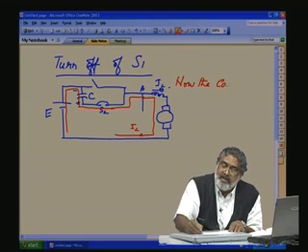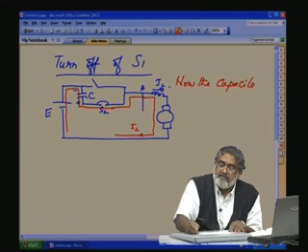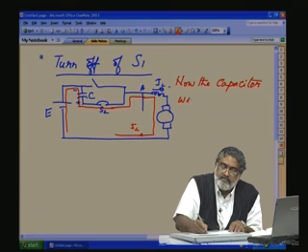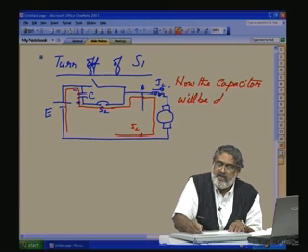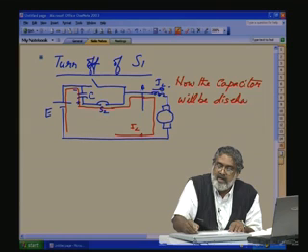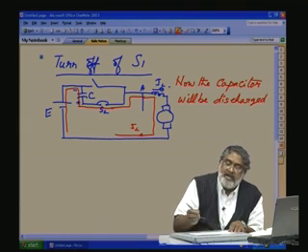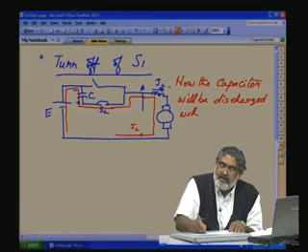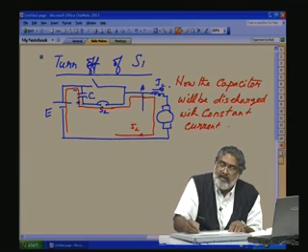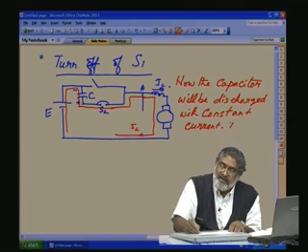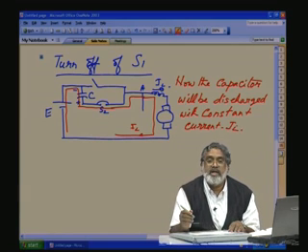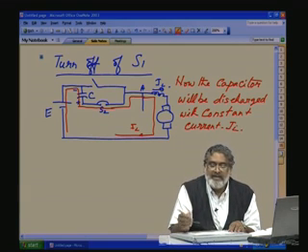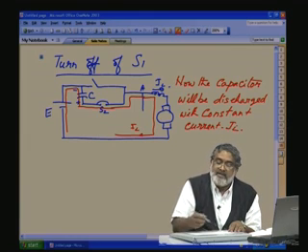Now, the capacitor will be discharged with a constant current equal to IL, a constant current that depends on the load, that is IL. So, the capacitor will slowly discharge, and again see, till the diode is turned on, the load cannot freewheel.